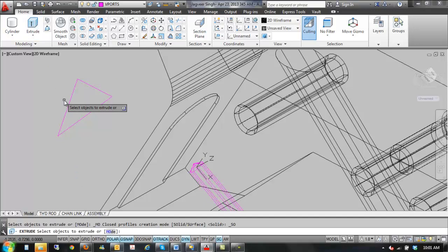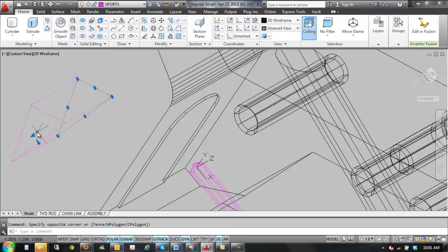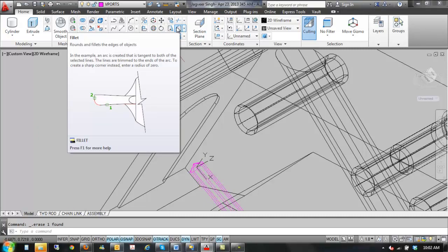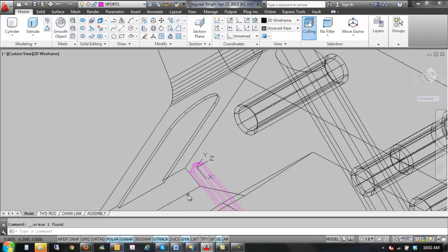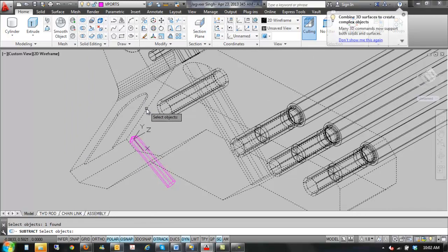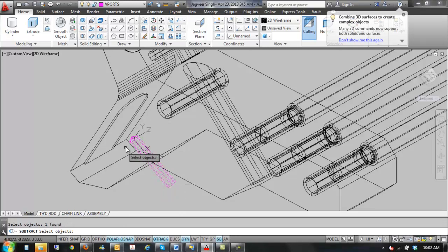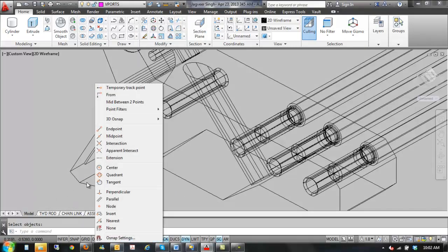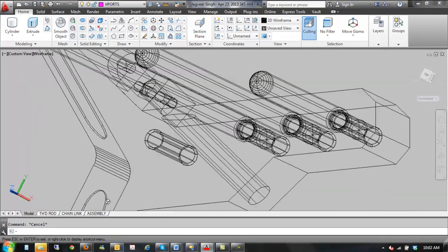But now as I extrude this, because it's a closed polyline, it's a solid, right? So if you see all those lines popping up, you got an opening somewhere. You didn't quite get the lines connected. And that's why I use the fillet tool, because it will extend and cut at the same time and make sure that I have closed corners. It's surefire. So let's subtract that. Subtract from here. And we'll subtract that and that object. I didn't have to join them together because I'm subtracting them both, but now I got a hole in there, right?